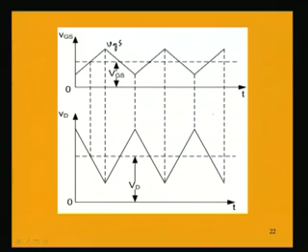It is amplified no doubt, but out of phase by 180 degree. Now, in the absence of the signal, for the DC VGS, we have the DC VD. So, this constant part is the DC value of the drain voltage, and on it is superimposed the AC portion, small v small d.